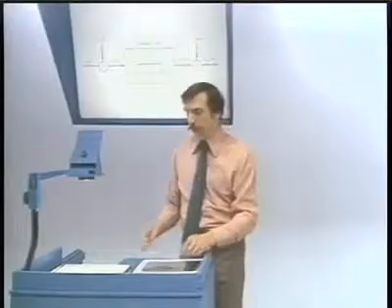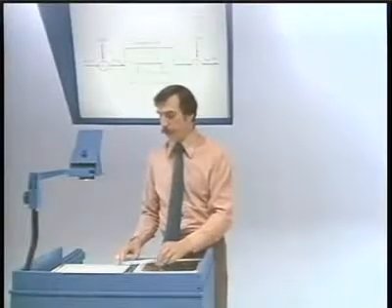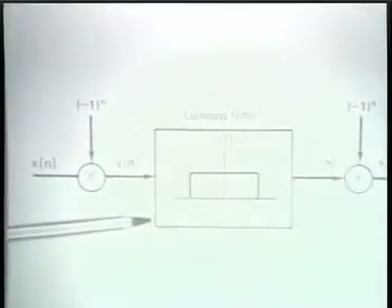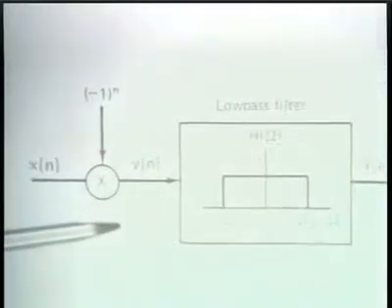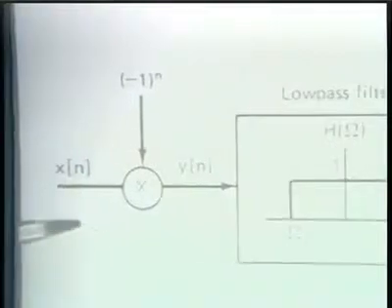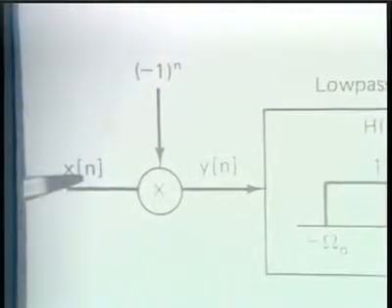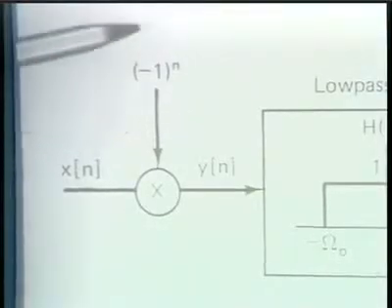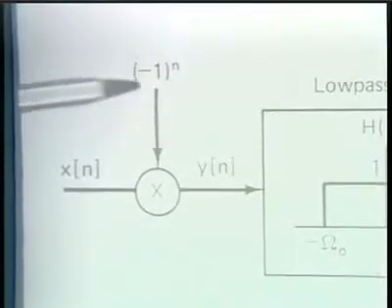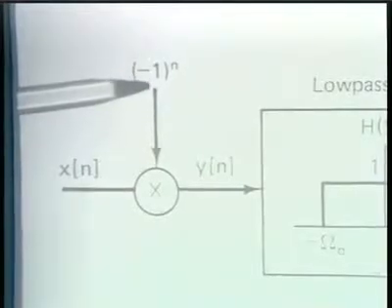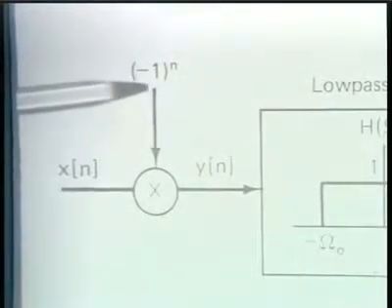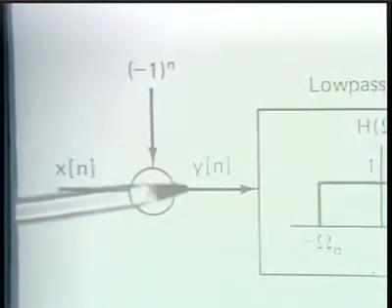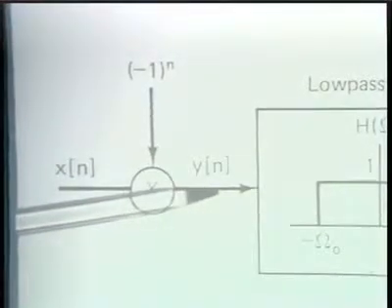We had originally talked about this when we introduced the modulation property, in the context of converting a low-pass filter to a high-pass filter. And the notion was that if we modulate the signal with a carrier which is (-1)^n, and that's simply a complex exponential or sinusoidal carrier with a carrier frequency of pi, then, in effect, that interchanges the low frequencies and the high frequencies.